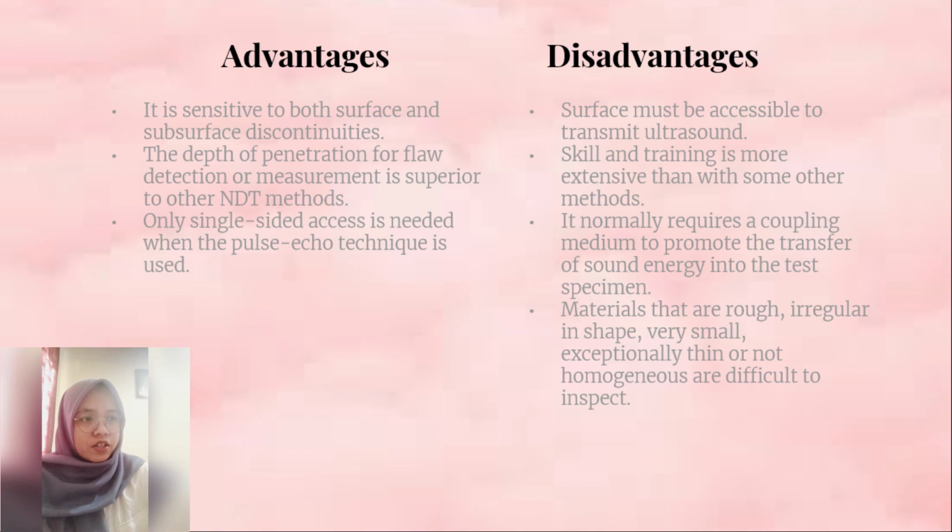The disadvantage of this UT method is that the surface must be accessible to transmit ultrasound. Skill and training are more extensive than with some other methods. Materials that are rough, irregular in shape, very small, exceptionally thin, or not homogeneous are difficult to inspect.